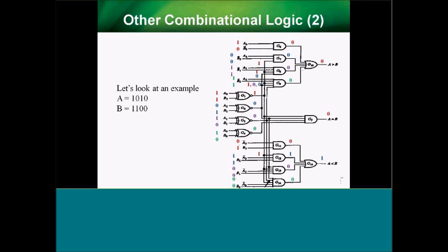But the idea here is if you take these two examples, A is 10, so it's 1010, and B is 12, 1100. You put those bits in there, bit by bit, and I've color coded them, and I apologize if some people have issues with seeing color. If you take the most significant bits, A3, B3, those are the same, so the comparator gives 1. But all the other bits are going to be different. Actually, for the last one, they're both 0. That's a mistake on my part. Down here, these are both 0, so that would have been a 1.